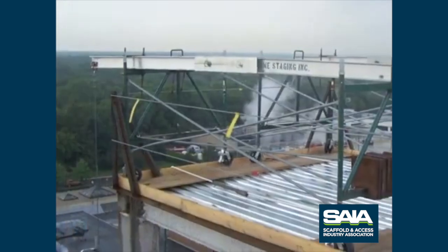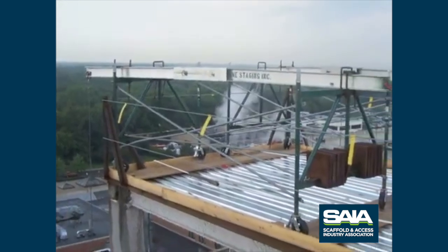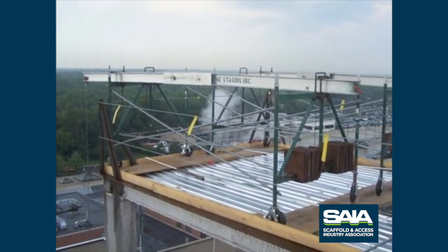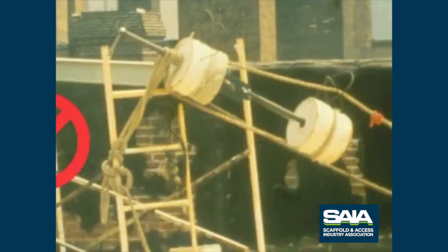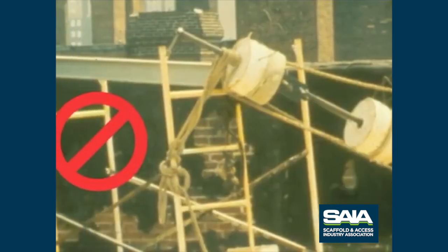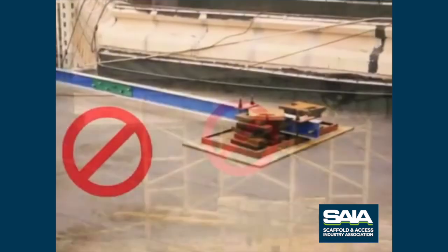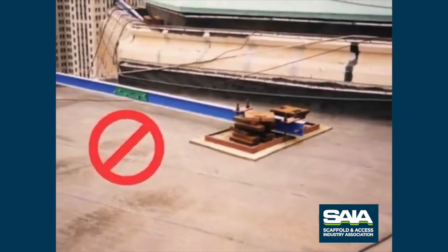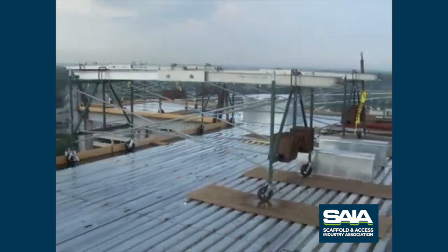The beam should be fastened to the bearer and counterweights should be within the confines of the scaffold legs to prevent overturning should the suspended load be removed. Here are some examples of an improperly rigged outrigger beam. Here are some properly rigged outrigger beams.